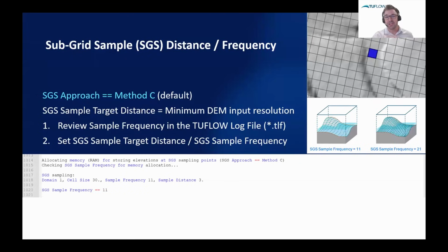This one change here reduced my simulation time from 5 minutes down to 3.5, and the model now uses 20 times less RAM. That's of special significance because the less compute load you require will determine what sort of hardware you can use to run your simulations. You can typically choose cheaper hardware on the cloud if you require less RAM.